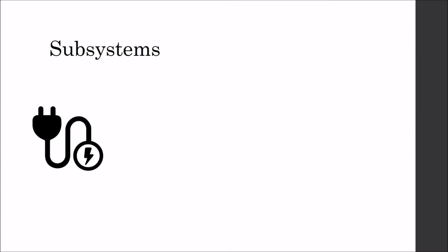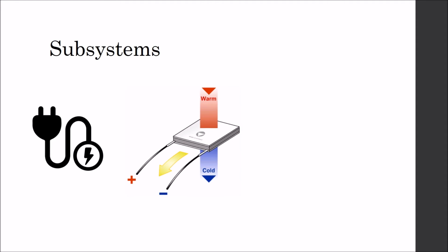A few other components are necessary for circuit operation. A power supply and voltage reference need to be designed to provide 5 volts and 2.5 volt references, and supply enough power for complete device operation. Currently, the device is expected to consume no more than 15 watts. The Peltier cell assembly will provide the cooling needed for the silicon photomultiplier. Although it does not create a lot of heat, the silicon photomultiplier still needs to be cooled down to its optimal temperature of -10 degrees Celsius.